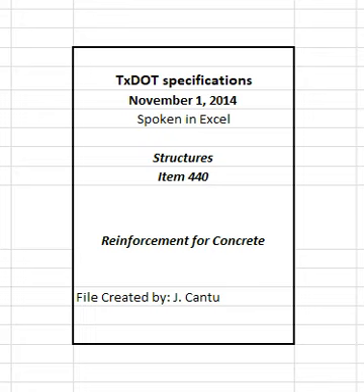3.6.3 Repairing coating. Use material that complies with the requirements of this item and ASTM D3963 for repairing of the coating. Make repairs in accordance with procedures recommended by the manufacturer of the epoxy coating powder. Apply at least the same coating thickness as required for the original coating for areas to be patched. Repair all visible damage to the coating. Repair sawed and sheared ends, cuts, breaks, and other damage promptly before additional oxidation occurs. Clean areas to be repaired to ensure they are free from surface contaminants. Make repairs in the shop or field as required.